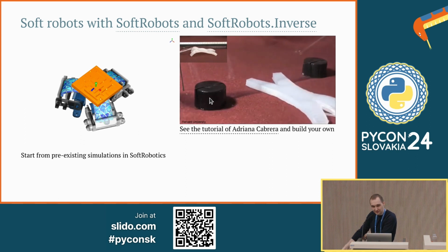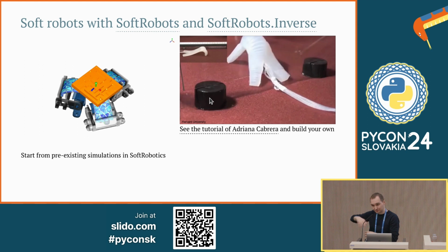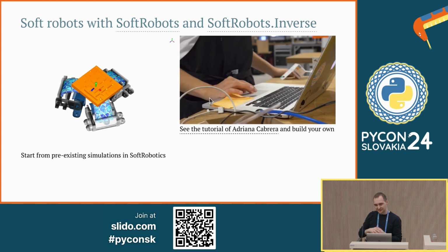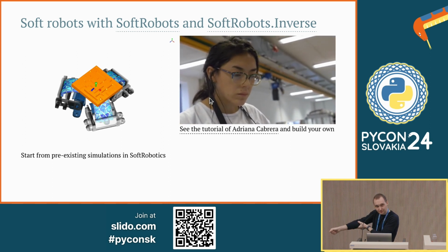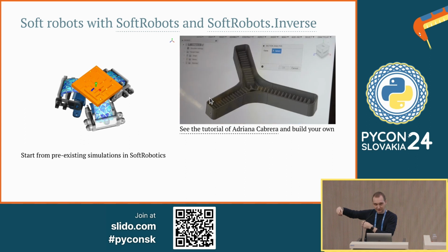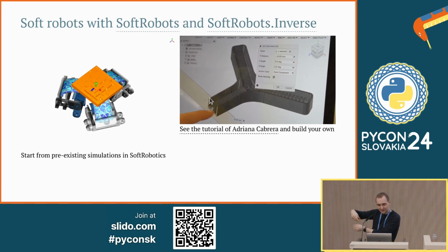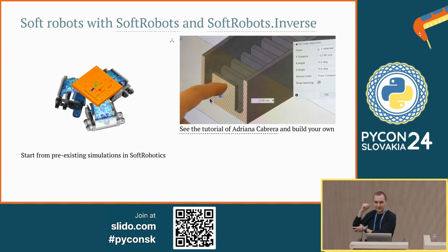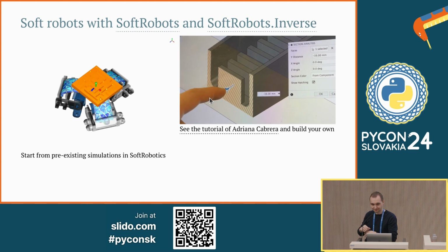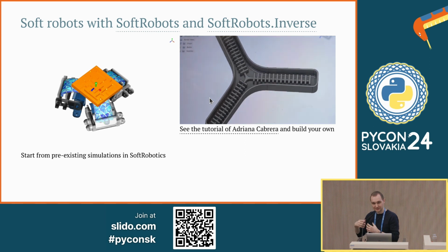the ones you see in car industry, where you have links joined physically together and everything has to move rigidly from one place to another, and then you compute the forward and inverse kinematics. So forward is that you know the orientations of the angles of the joints, and you project it to the position, so to the XYZ of the end part of the robot. The problem of inverse kinematics is that you have the XYZ position of the robot, and you want to know what are the joint angles that the robot has to achieve to get to the position. That kind of works well enough for rigid robots, but it starts to be tricky for something that's soft.